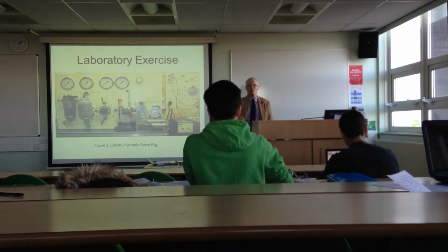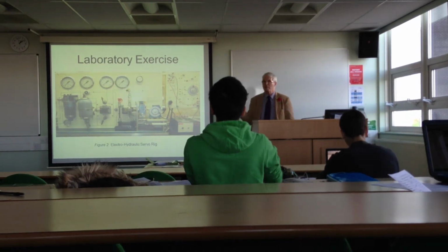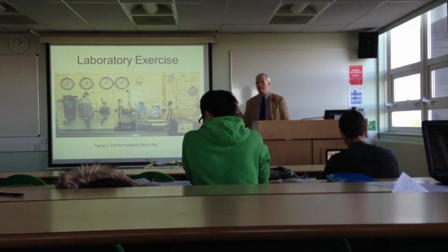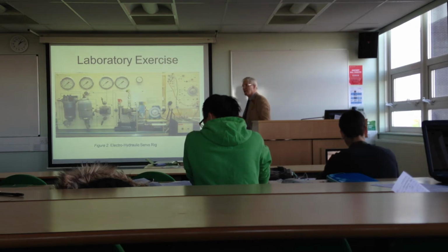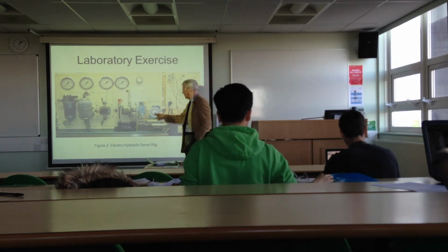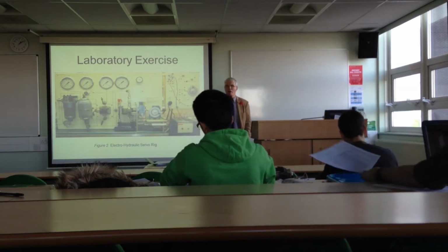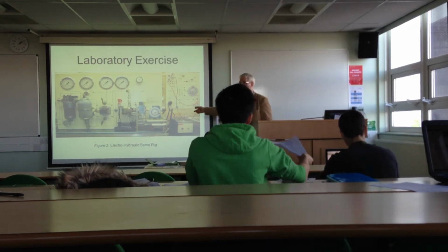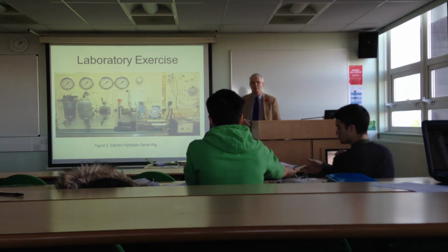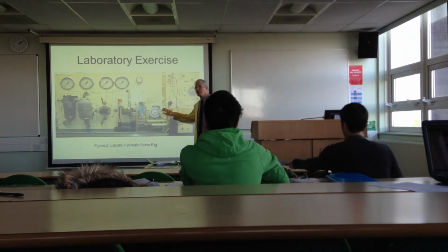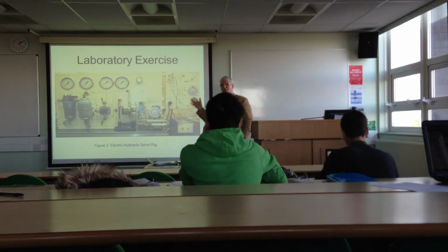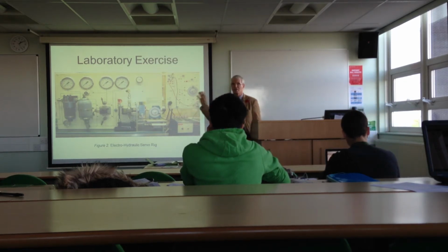It's effectively a little voltage generator. It's very precise, and the voltage it produces is proportional to the speed. Now, in the past, we have asked students to time how long this takes, say, for 50 or 100 reps, to work backwards and to try and confirm the constant for that one. But we were told that gives you 26 millivolts per radian per second. So basically, as long as we get the voltage that it generates, we know how fast the motor is turning.